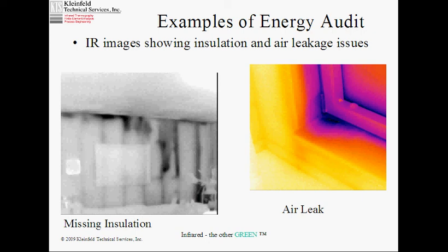Those large cold areas are problems where the insulation either was not put in, was put in poorly, or has sagged since it was put in. You'll note, by the way, that you can even see the studs through the picture hanging on the wall. Not as clearly, but there's enough difference that the temperature difference is transferring through that as well. It's better to look at the bare wall when and where you can.